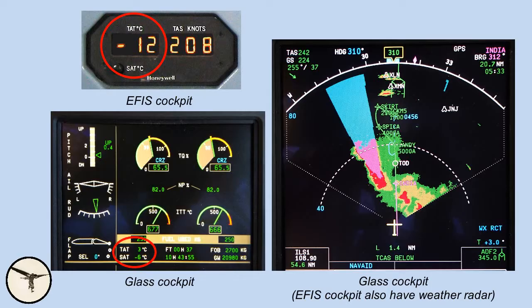Your first line of defense is the temperature indicator and the weather radar. The echo from the weather radar varies in intensity as a function of the droplet size, composition and quantity. What you should have in mind is that even a green radar return may result in severe icing. I have experienced just that.